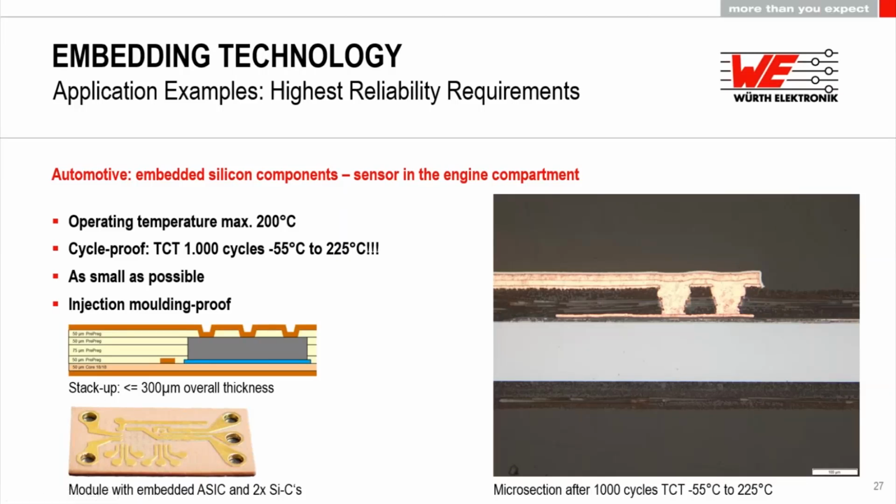And on the right side, you now see a micro section after the 1000 cycles in the temperature cycling from minus 55 to 125 degrees, and you see that there are no cracks and no other failures. The only thing you might see is that the material, the dielectric itself, darkened a little bit, so it's not that reddish brownish as you see in the bottom left. It's more dark brown when you look at the real module.